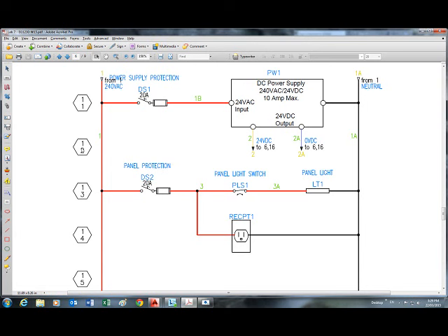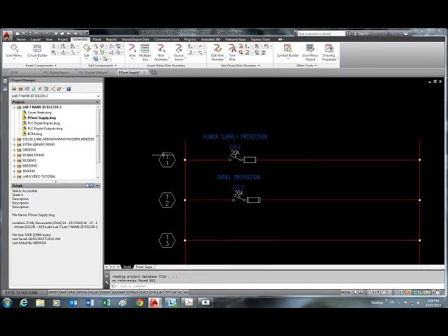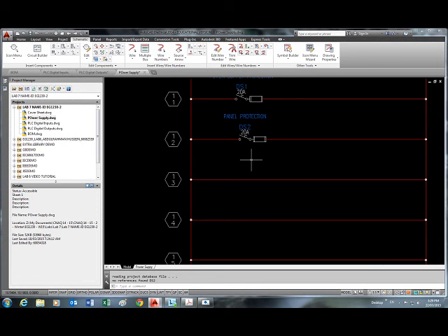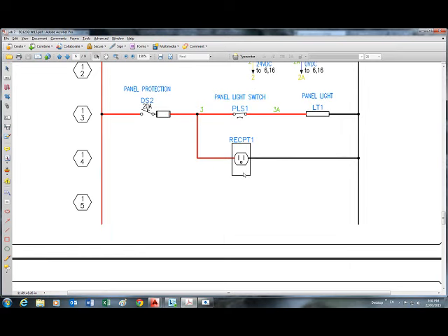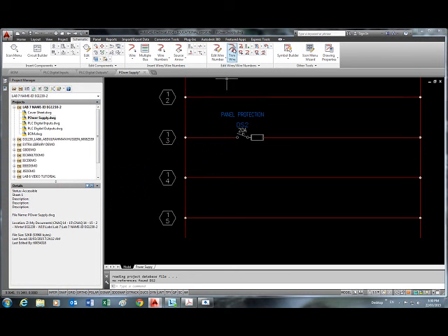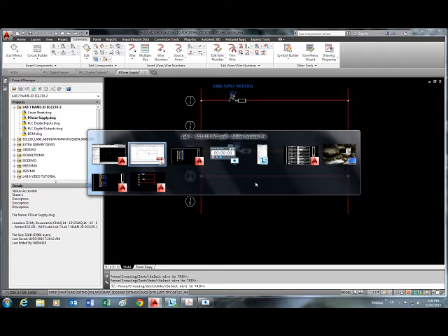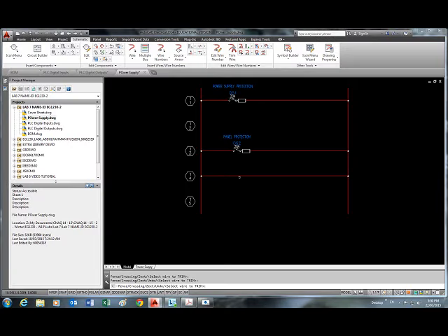Alright, notice that rung number 2 has nothing, so this should not go on rung number 2. So I'm going to right click and then move component to this rung. Notice it has rejoined this wire and properly connected this component here. Notice again that 5 is not there, so I can trim both 1 and 2. Okay, now I can do the receptacle.